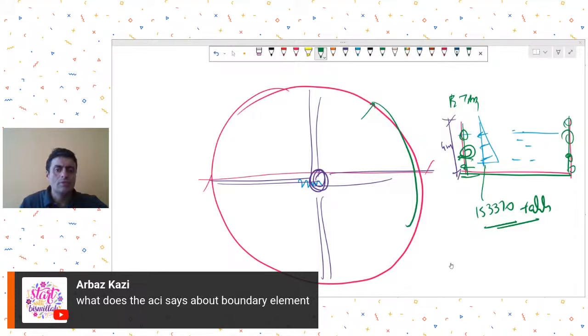The main reason was that the floor modeling options were not so great in STAAD back then, but now in ETABS, you get good options for shell modeling also. So the behavior of the slab is closer to a shell-like behavior rather than a membrane-like behavior.